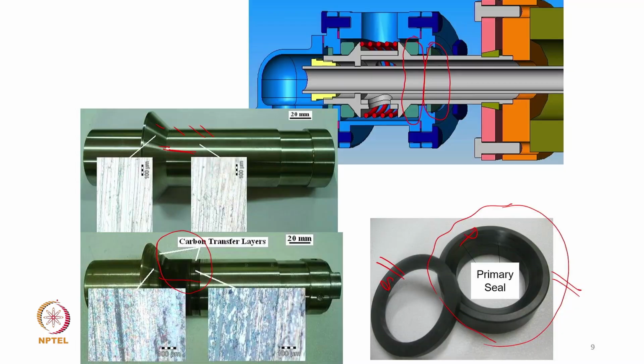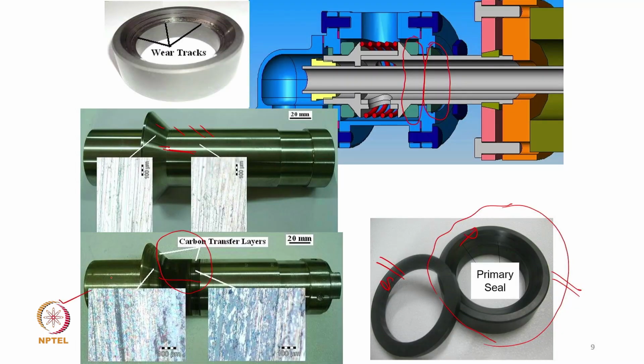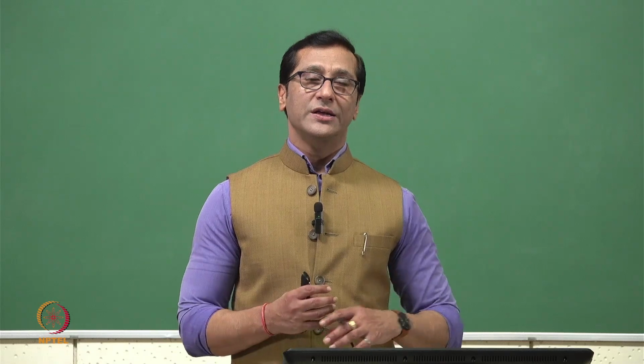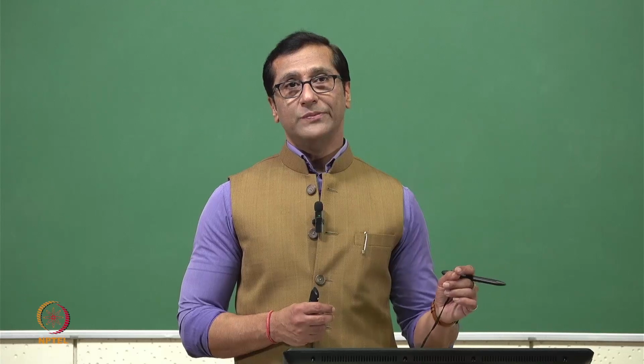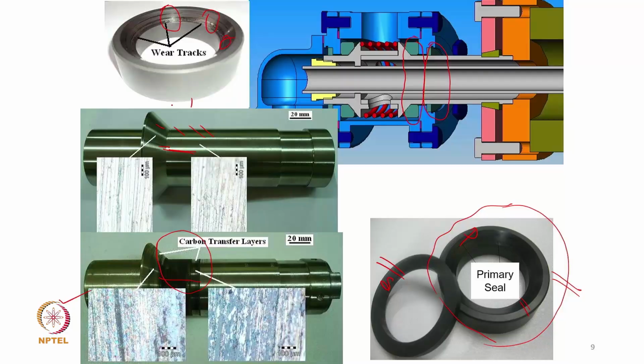And that's where the good solution comes from. Of course, if you apply much higher pressure, because we know the carbon graphite cannot sustain high pressure, then you can see that more burning is happening, or wear is much faster. So if you apply more pressure from the back end side, so that this comes, and more interface happens over here, the coefficient of friction will increase, and the wear rate will increase.